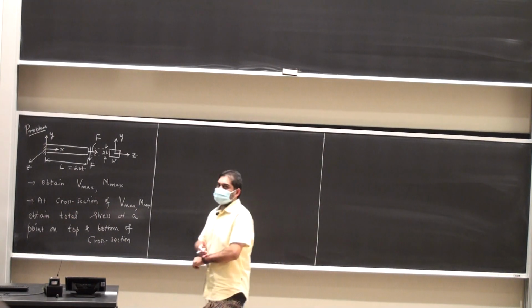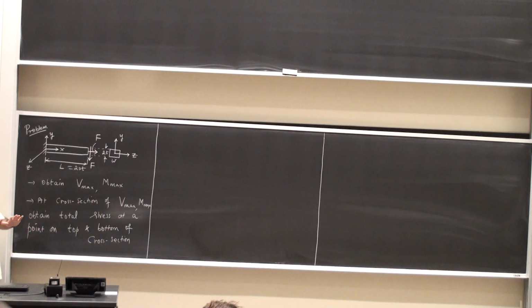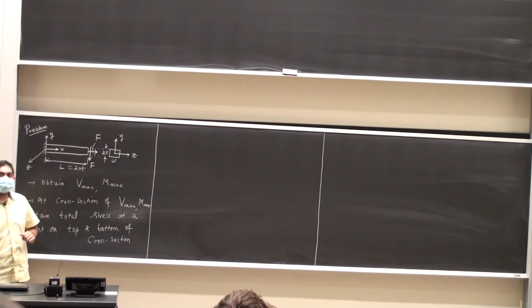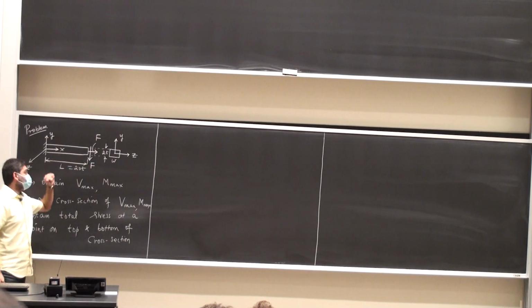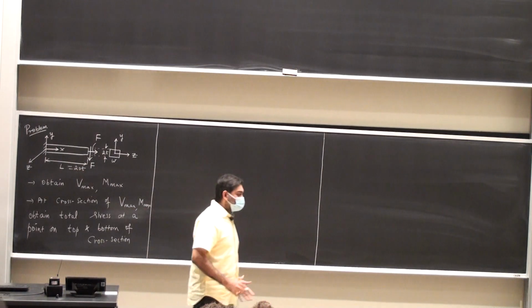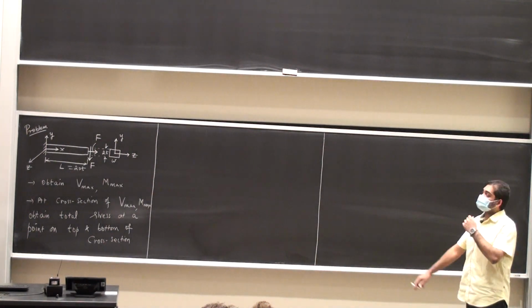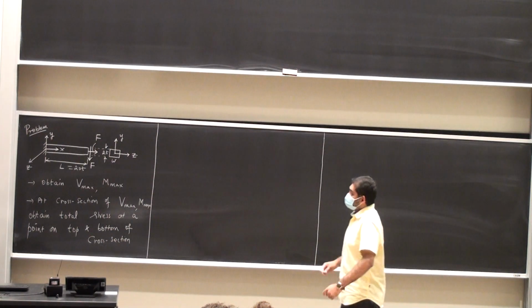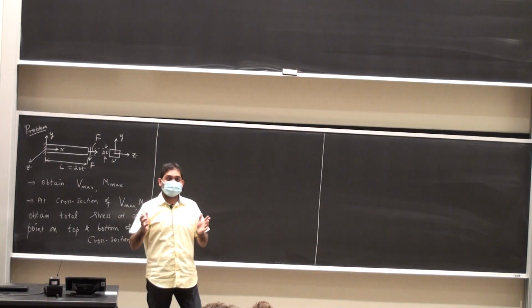So, fairly standard problems. This is how we will be looking at problems from now on: we're going to have a combination of loadings. There's going to be a force which is in essence creating a shear force. Then I'm going to have some kind of an axial force, and there will be a state of stress created due to a combination of all of this. I'm going to have bending stresses, I'm going to have shear stress, and importantly, because there is a normal force acting, I'm going to have an axial stress as well.